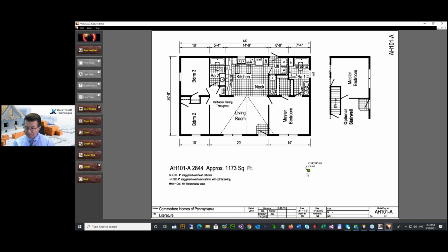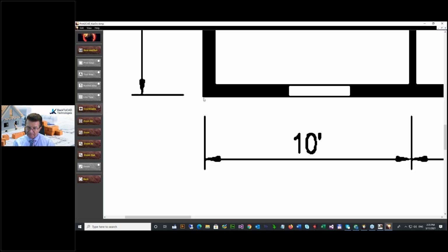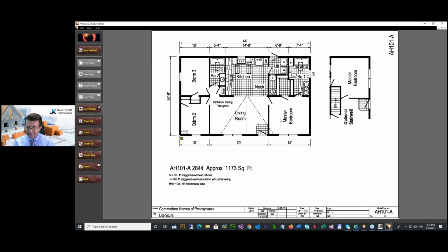But you need more precise calibration points here. For example, you can put this calibration point here at the corner. So calibration point, and I decide that this will be my coordinate 0, 0. And if you have this rectangle as a corner, we will snap this rectangle during the conversion. Okay, 0, 0. Now, if you want, you can go here to this corner. Okay. And here you can calibrate this point too.